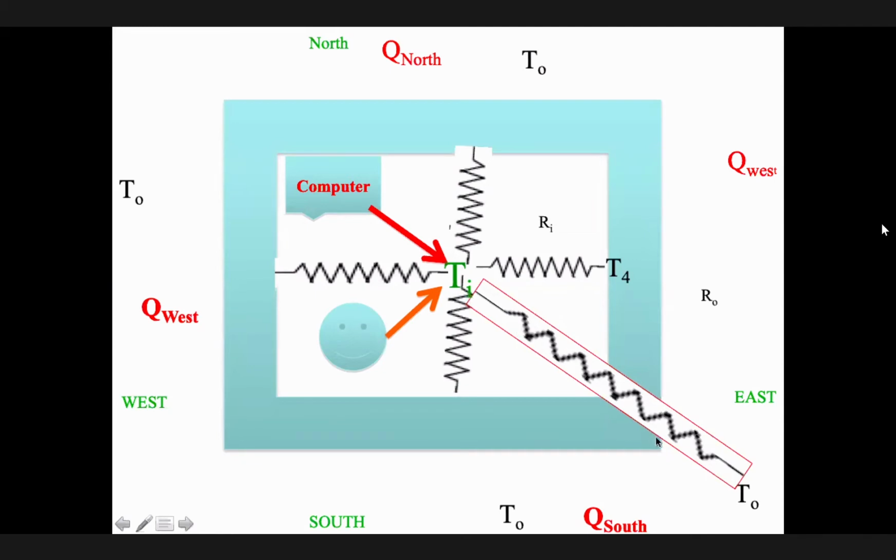That's multiplied by m, the mass flow rate. Mass flow rate you can calculate because you have the volume of the room and you have the air exchange, times Cp and so on. Plus, the energy that comes from people. Again, you can use a number like 65 watts, you can use 70 watts, depending on the level of activity that you would like to consider. Again, keep track of time, because sometimes you have 2 people, sometimes 1 person, sometimes no person. Plus the energy from the computer. Again, you can look at your computer to see how much energy it has, and you can add this one. Therefore, this is the energy balance for room air. Did I answer your question, sir?